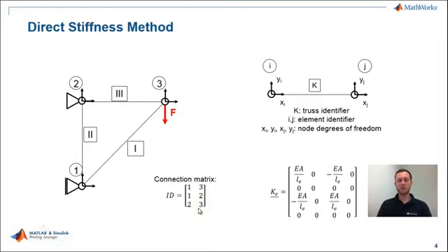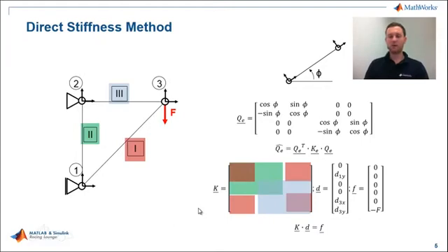So as easy as that, you want to create the system matrix now. The only thing that might happen to the stiffness matrix of an individual truss is, okay, the truss is rotated, for example as truss 1 here. That means nothing but employing a rotation matrix to the stiffness matrix of your system. This means transferring the local coordinates to the global coordinates. And then we are already ready to go to fill up the system equations. So we have seen the local element stiffness matrix, and we want to put that in the global system stiffness matrix.